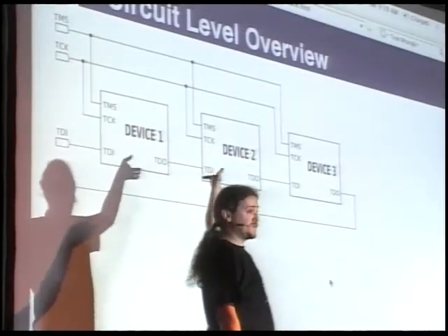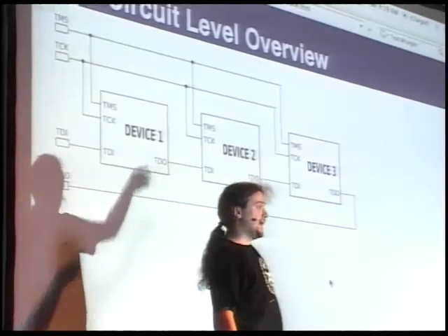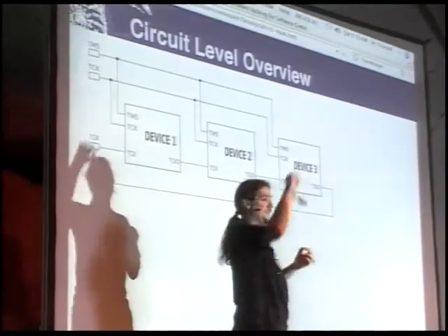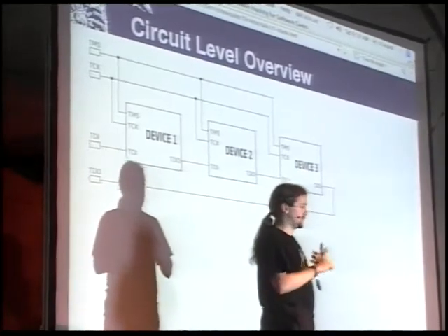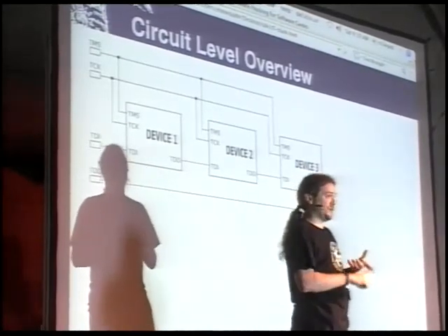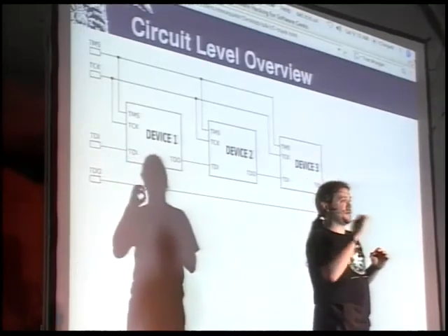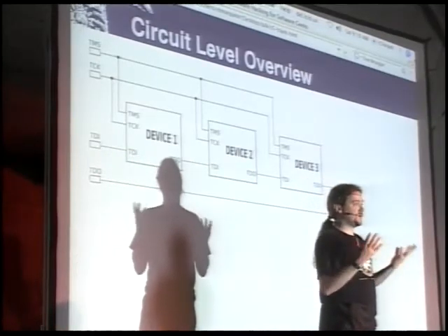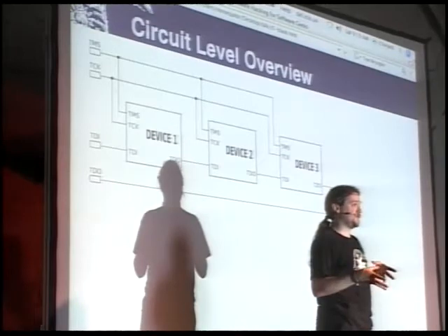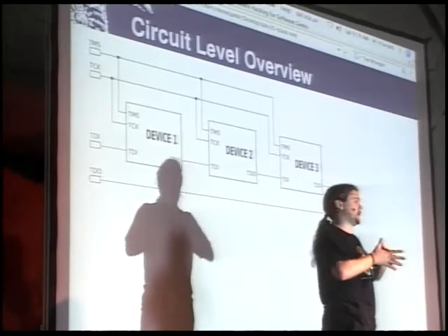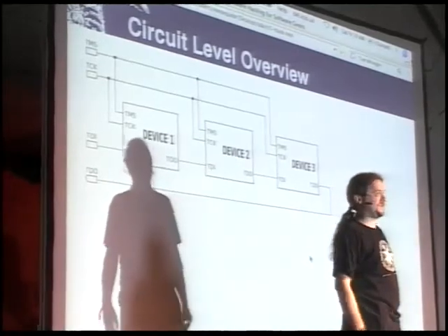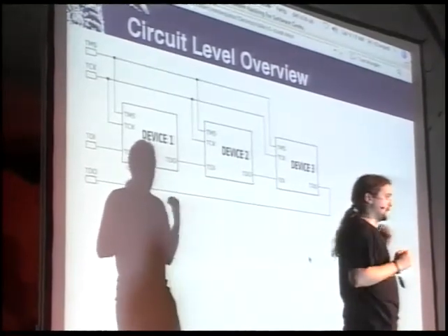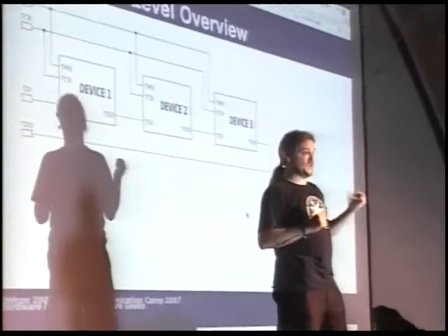This is essentially a shift register, if anybody knows what that is, that incorporates every pin of every device in the circuit. This means you can set, under software control, the state of any device, or the state of any pin of any device in the circuit. So you can do what-if scenarios where you can say, well, what if all the data lines went high at once? You just clock in a whole bunch of ones until they're at those data lines and then see what happens. Another use is getting flash in or out.